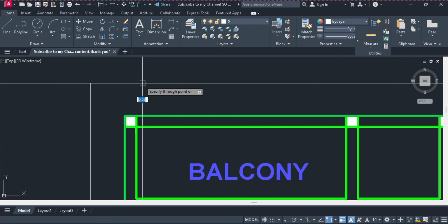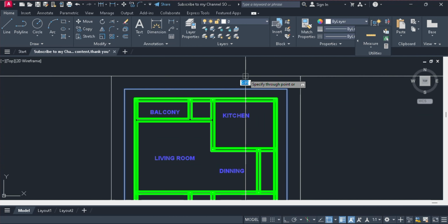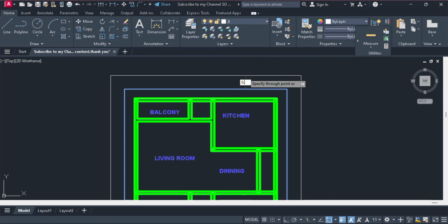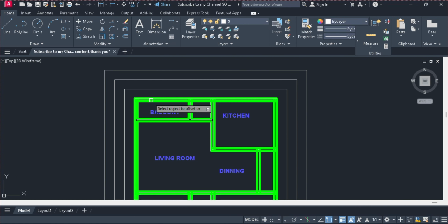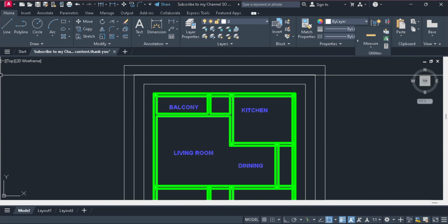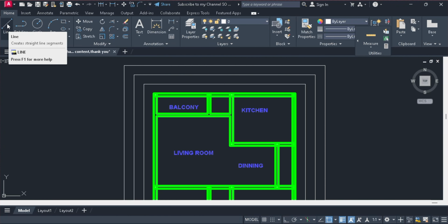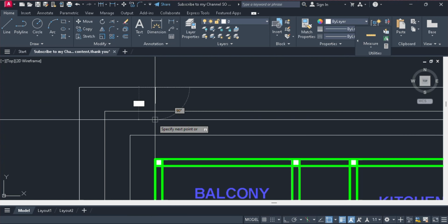want to offset it by 0.7. We equally want to repeat the offset command by offsetting it again by 0.7. You offset it again the third time by 0.7. Press enter, and that will be done. Then you come back and delete your initial point. Then you come back and delete the initial line you drew. To be able to draw your axis line, you're going to click on the line command here. You mark a point up this way and you draw it down.